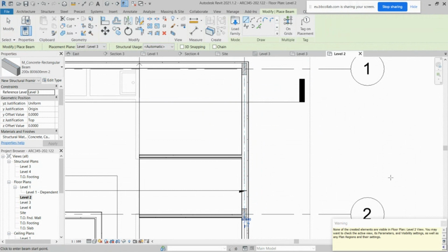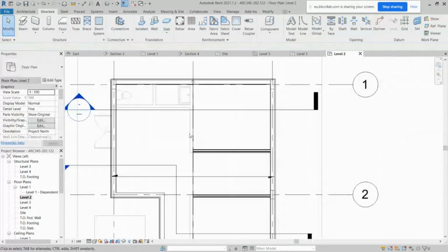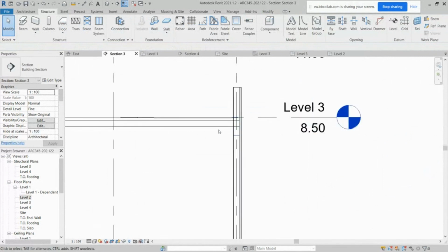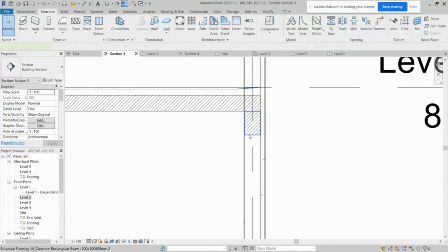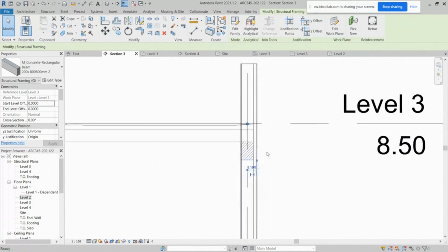And you construct your beam. It's not shown here because it's above the cut. That is fine. And hopefully now it draws it for us. Yes, here it is. Now the warning that we have seen is because of the overlap. You see that the reference line of the section was respecting level 3 without any projection or offset from it. That's why it overlapped with the slab.